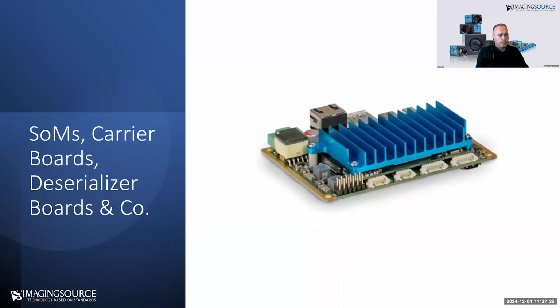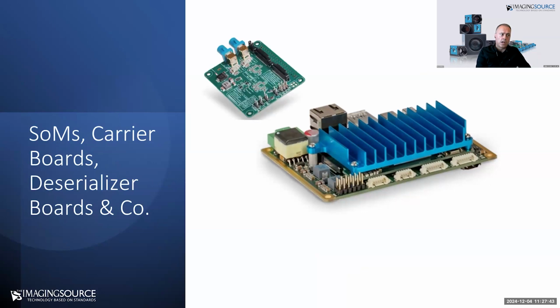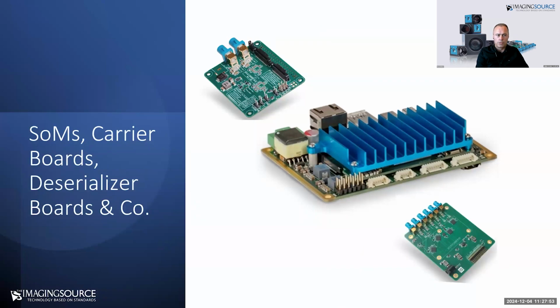So once again, embedded vision means SOMs, so system on modules, and carrier boards for all the peripheral devices. And I just want to highlight once again, if you are going for, let's say, 15 meters of cable length with GMSL2 or FPD-Link, then of course you have to consider deserializer boards too.